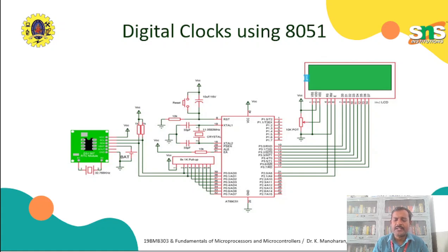First, inside the program, we need to initialize the time for the RTC. Today's date, time, seconds, everything should be written to the RTC one time. Once you write it, this information will be kept in the RTC. Automatically the seconds will increment, and then the hours, minutes, day, month and year will also increment based on that information.